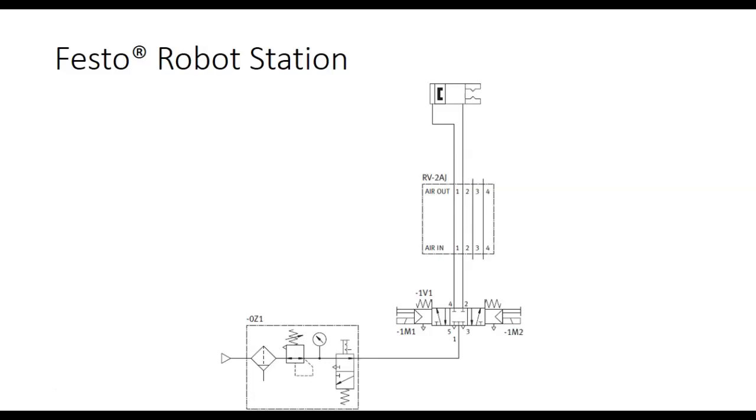Now notice, pressure side is odd, working side is even. You understand? You understand, Jess? Yeah. And it's spring centered. So if I de-energize this guy and de-energize this guy, the spool is going to shift back to the center, which is the way all three position valves work, by the way. They just usually don't draw the spring.